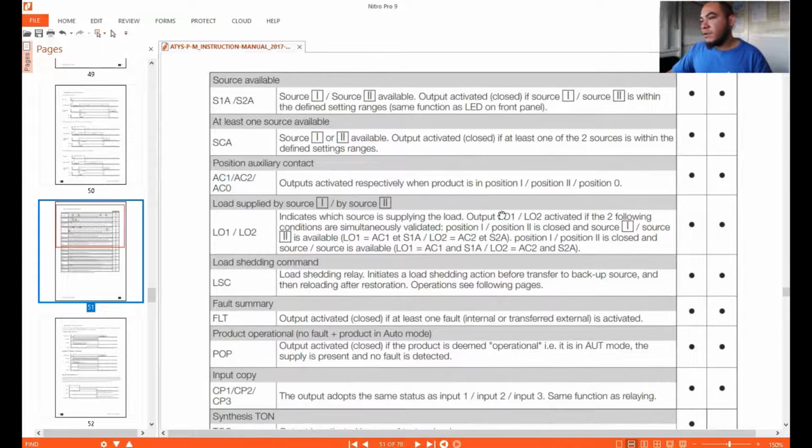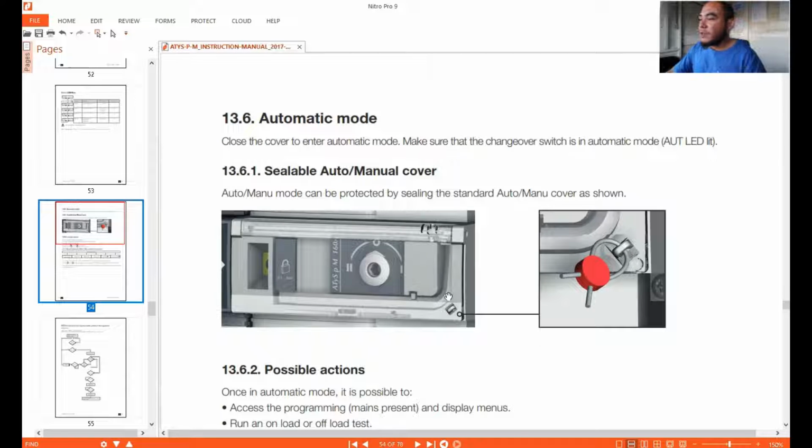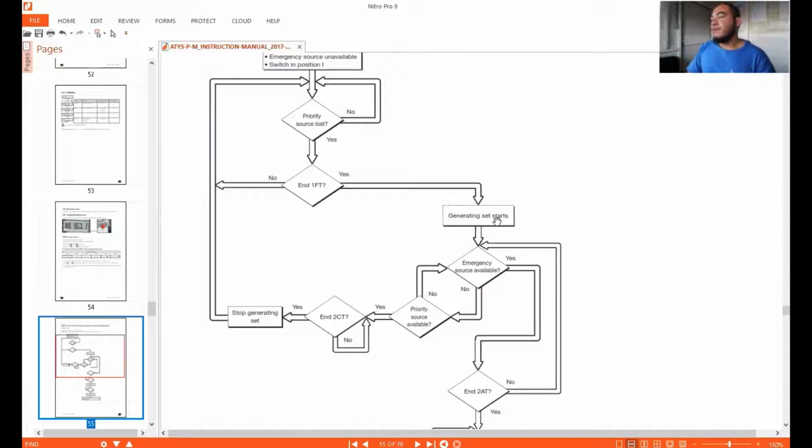So leave the default configurations on that, so it will not be more complicated and problematic during the installation and the tests for this ATS. As I told you, just do the configurations for your voltage and the frequency of both of your source number 1 and 2. That is the priority to adjust in order to work on this ATS. The rest is not necessary for the adjustment.